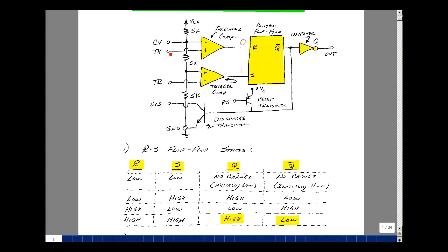Okay, the threshold pin is the capacitor voltage, and that hasn't reached 2/3 VCC yet, so the voltage across here again is still negative, so we get a 0. But now the trigger has returned back to a number that's greater than 1/3 VCC. So now the difference here of 1/3 VCC minus a number that's bigger would be negative, and that would now make this go low.